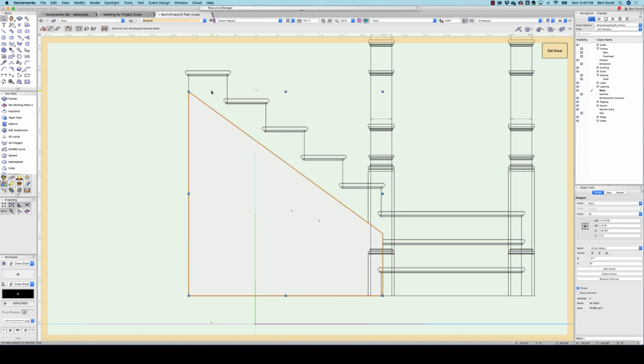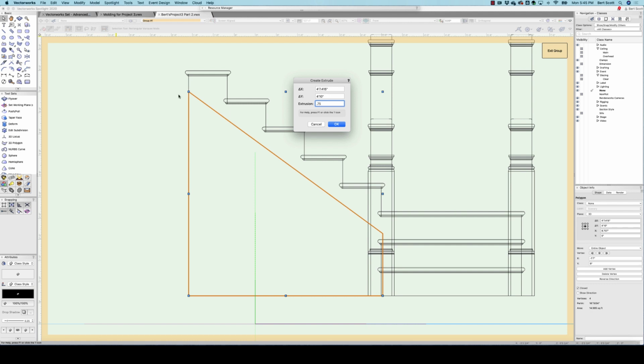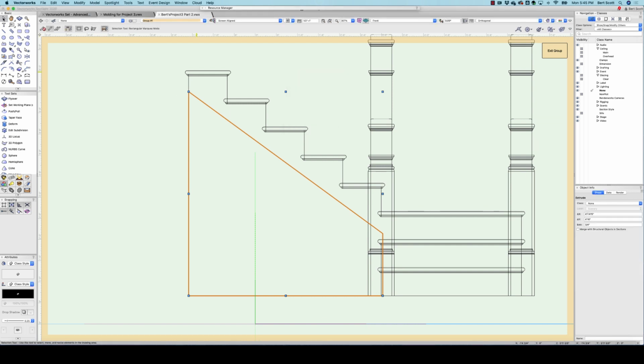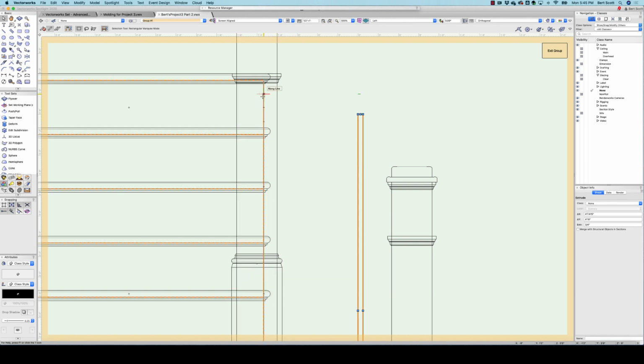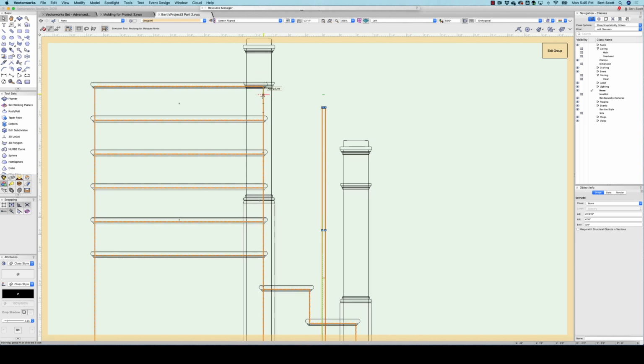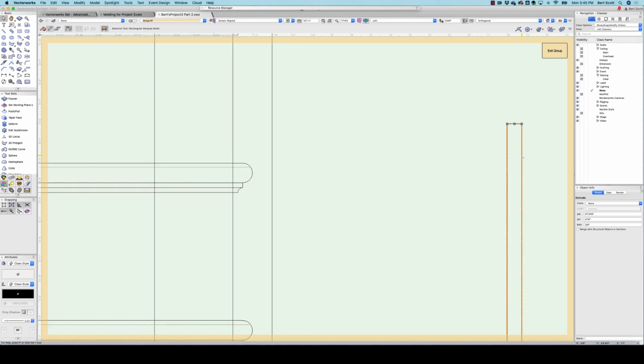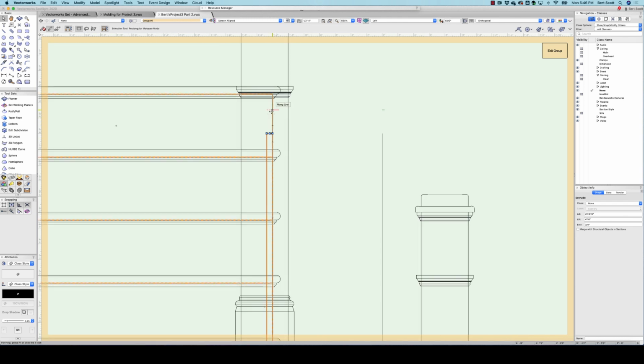And because I want this piece of molding to be 3/4 of an inch thick, I'm going to extrude the negative space 3/4 of an inch. Model, extrude, 0.75. Okay. Then I'm going to go to left view, and I'm going to line up the front face of this with the front face here. So I'm going to grab this by here, then I'm going to hold down Shift, and I'm going to move over until I intersect there.